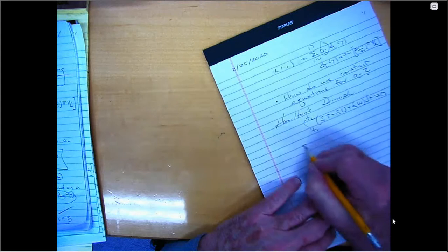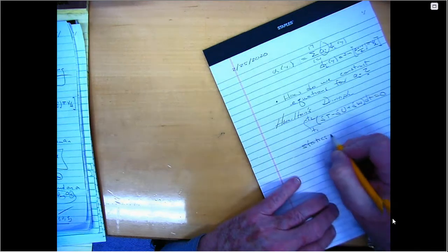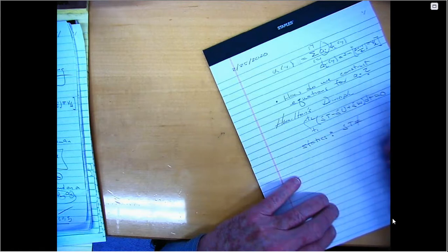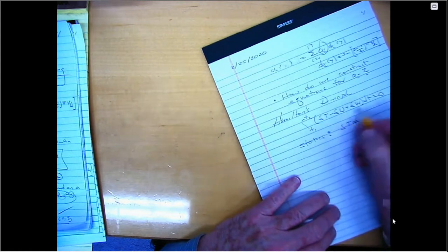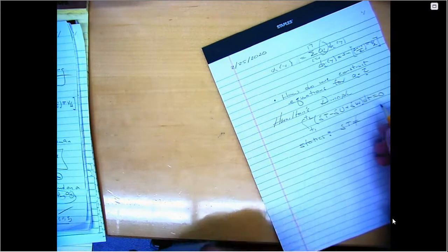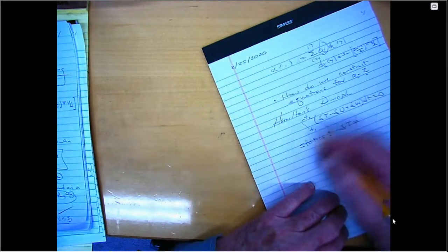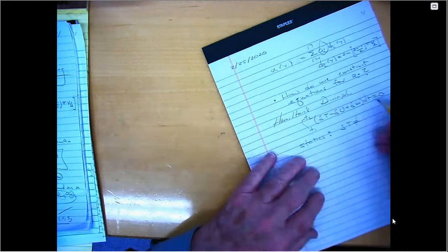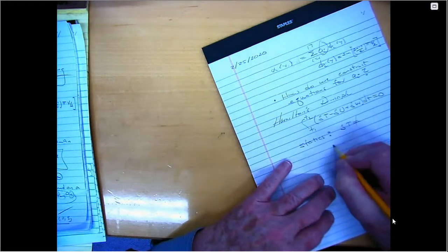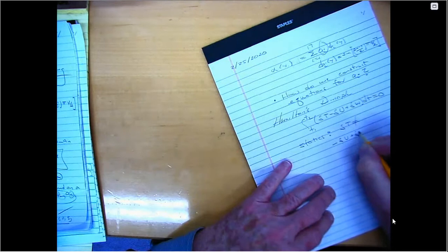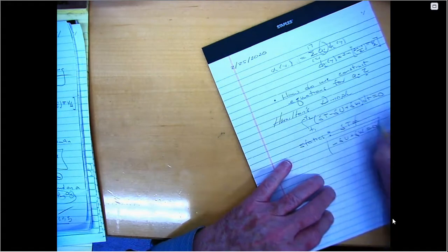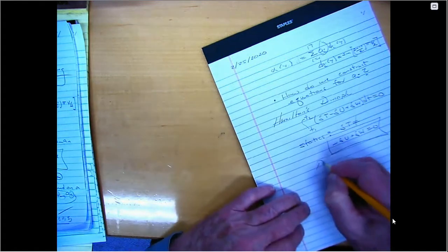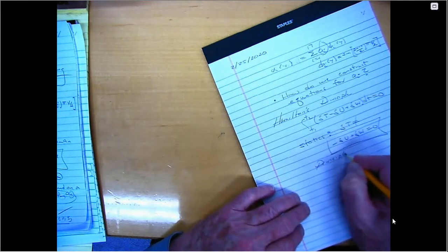But in statics, there's no delta t, right? So we can forget about delta t. And since none of these other things are allowed to change in a static formulation with time, this integral from T1 to T2 just gives me that time interval, but that's just a constant, and therefore this reduces to minus del U plus del W equals 0 for statics. And this is known as the principle of virtual work, right? So another thing you could do is just start with the principle of virtual work.